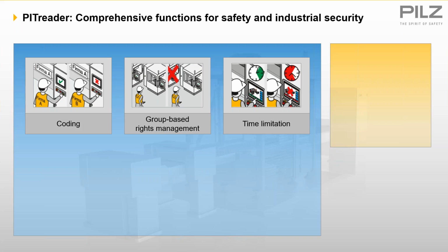If the operator hasn't been retrained, the key would just not work until they'd had the training and you'd revalidated the key. You could also do it for contractors or any visitors on site. You could issue them with a temporary key with different group and permissions, and again, that could be time stamped for the length of time they're expected to be on site.